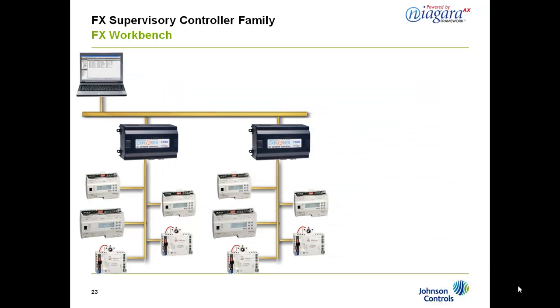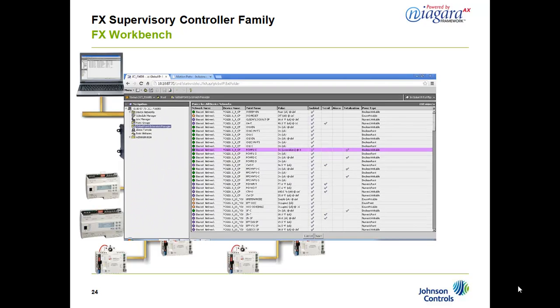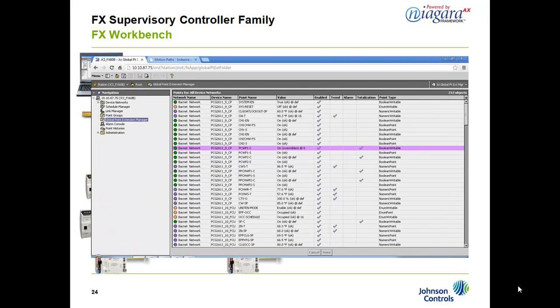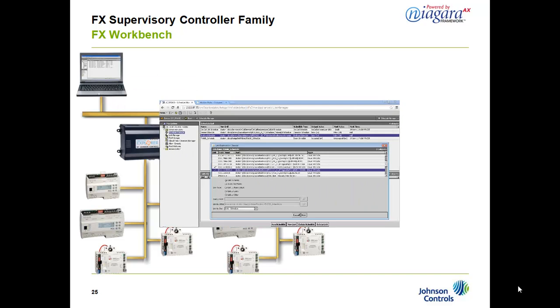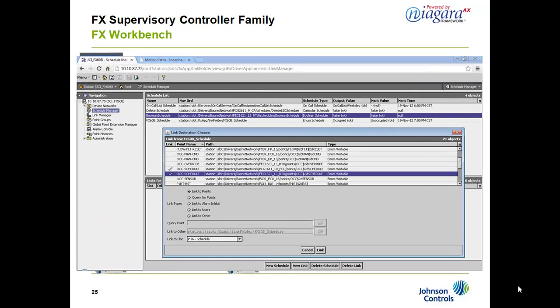FX Workbench also includes a point extension manager, which provides an easy-to-use, check-the-box mechanism for adding alarm, history, and totalization extensions to points. FX Workbench includes easy-to-use check-the-box link managers for linking points to a schedule, for linking points together for data sharing, and for organizing points into user groups. These are significant time savers for those responsible for engineering and installing FX supervisory controllers.